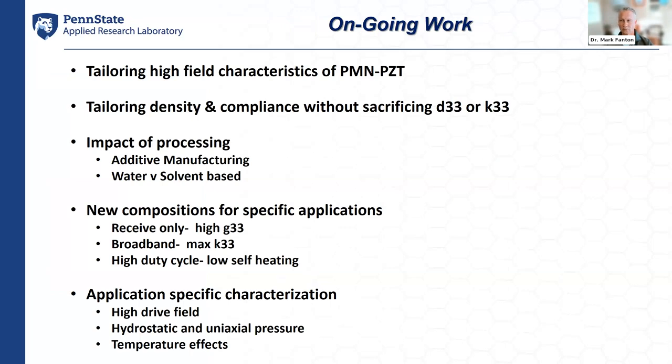Ongoing work for us here at Penn State, we're continuing to explore and try to understand and tailor the high field characteristics of the PMN-PZT phase space. Certainly for very high drive acoustic applications, that's of interest. We are actively exploring the ability to tailor density and material compliance without sacrificing D coefficients or coupling coefficients.